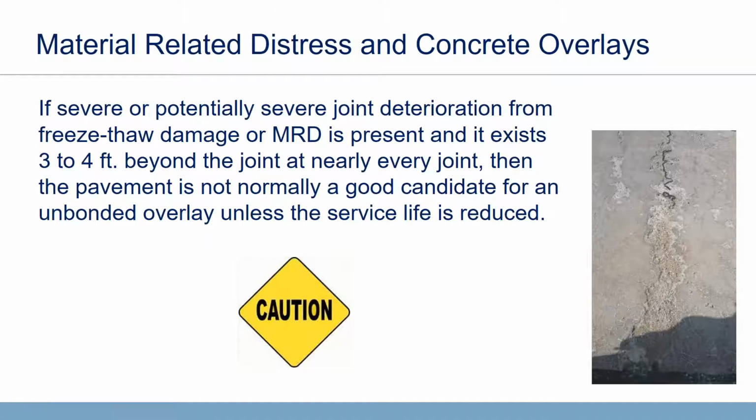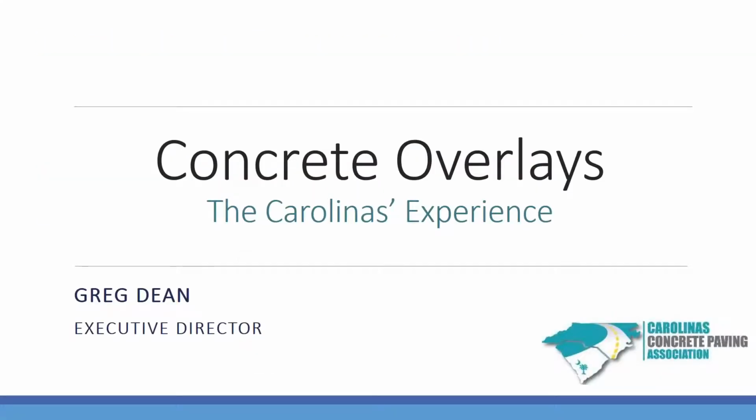We already talked a little bit about materials related to stress, and I'll just say that, again, we have done some overlays on that. They typically will not last as long as a material that had no aggregate issues or reactive issues in it, but if you're looking for a 15 to 20 year fix, I think you can certainly design an overlay that will work in many of those cases.